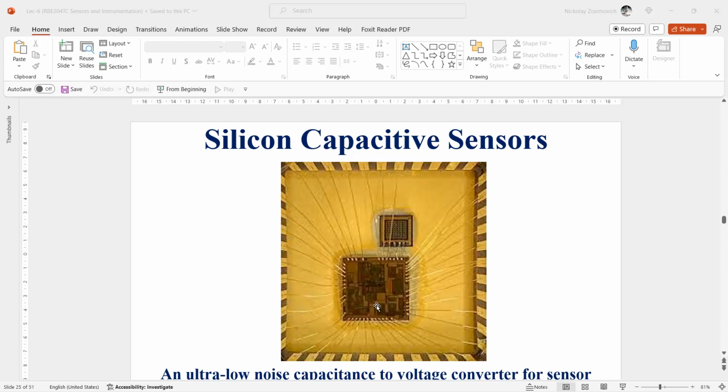Accelerometers get much attention because the force is introduced simply by the inertia of a seismic mass, fabricated on the same chip. Capacitive sensors for other measurements are also considered to be implemented in MEMS technology, for example, the angular sensor. From a technological point of view, however, a capacitive sensor is more difficult to realize compared to its resistive counterpart.